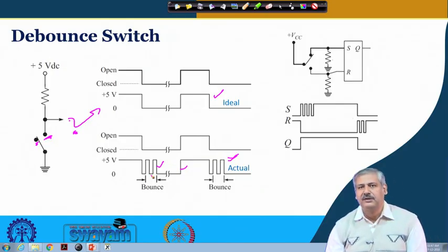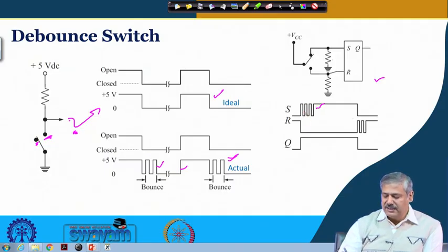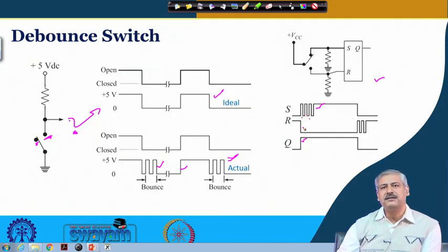So, for that we can use an SR latch, right. In the SR latch, the switch is connected to one of S and R. When it is disengaging from R and connecting to S, there is ringing over there. Whenever that happens, with 1 and 0, the output becomes 1 because it is getting set. After that, when S ringing occurs, it becomes 0. So with 0, 0, the previous state is retained. So, there is no issue with that.